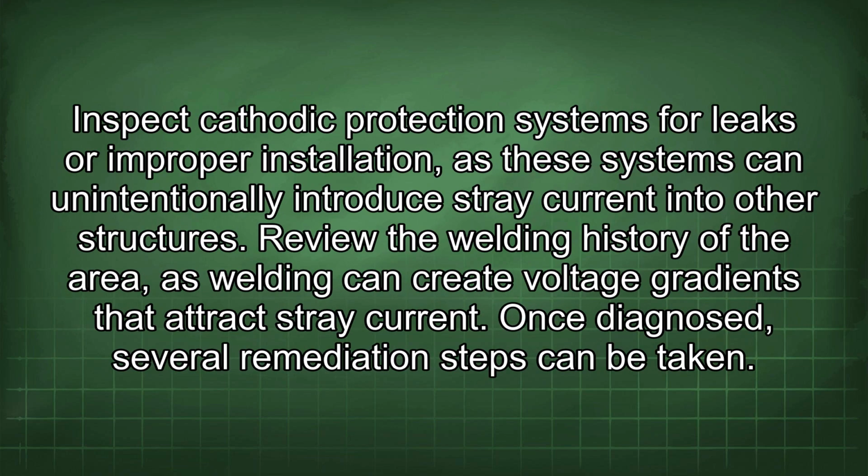Inspect cathodic protection systems for leaks or improper installation, as these systems can unintentionally introduce stray current into other structures. Review the welding history of the area, as welding can create voltage gradients that attract stray current. Once diagnosed, several remediation steps can be taken.